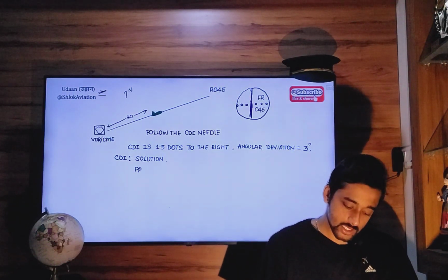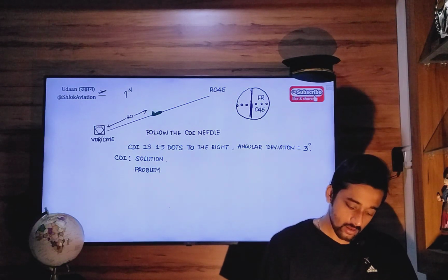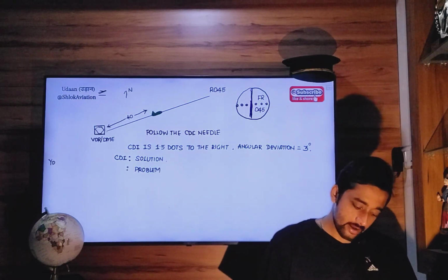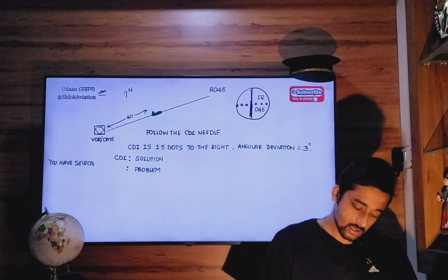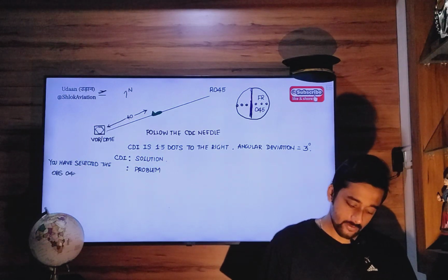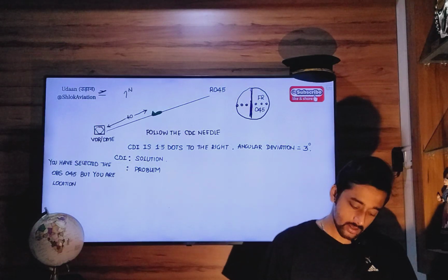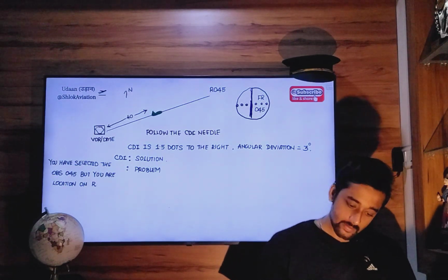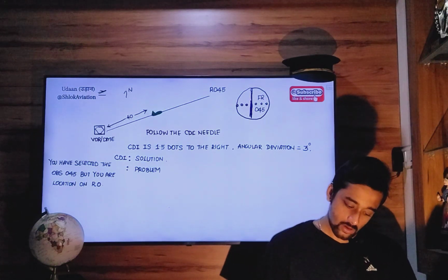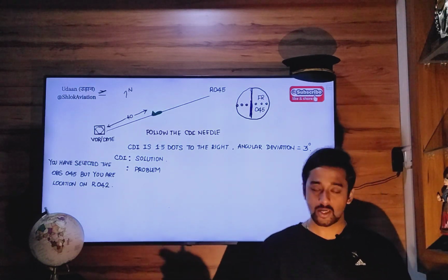The problem is you have selected the OBS 045, radial 045, and your position is located on radial 042. This is the problem.